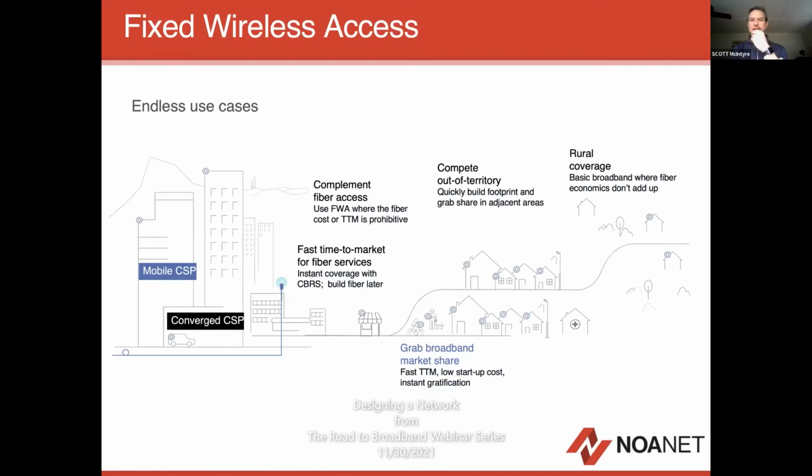Yeah, and there was a question that came up earlier about millimeter wave. With the very high frequency, you can get a lot of bandwidth. We're now pushing 10 gigabits over a single channel, over short distances, half a mile, maybe a mile. But a half mile is still pretty far. You can get from building to building, across a river, across a railroad track. You can do a lot of things with a giant pipe over a short distance that are very reliable. There's an old saying that any idiot with a backhoe can cut a fiber, but it takes an act of God to fade a microwave path.